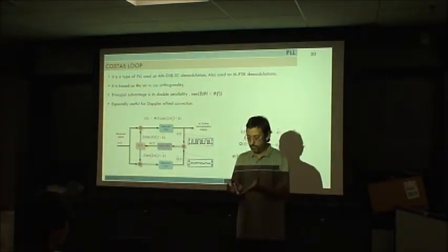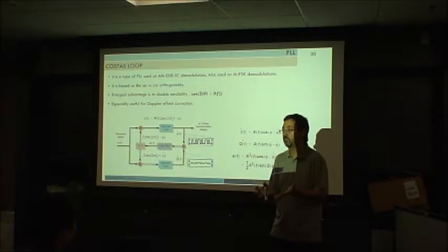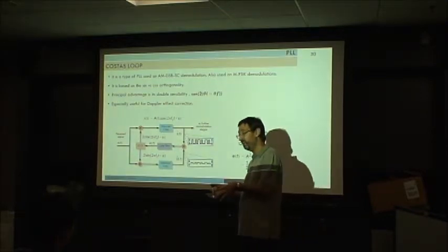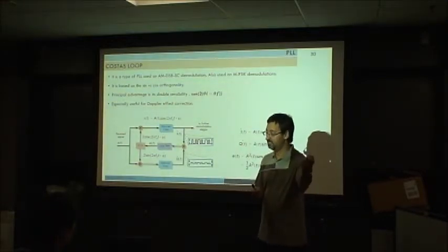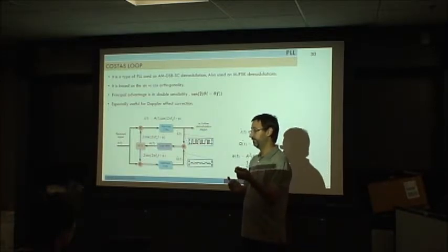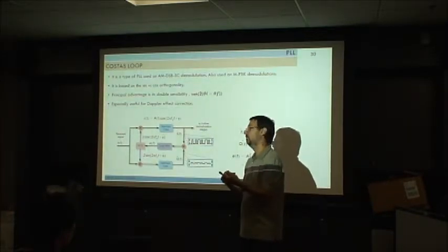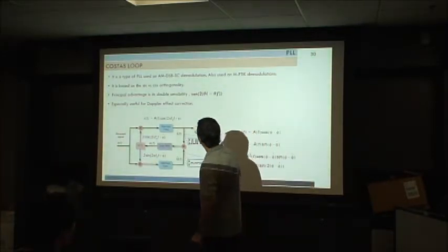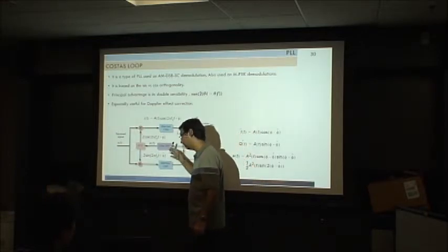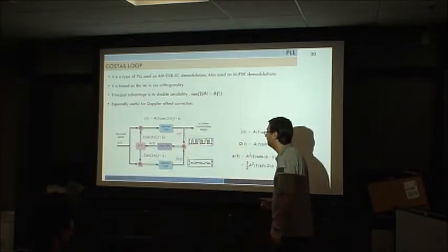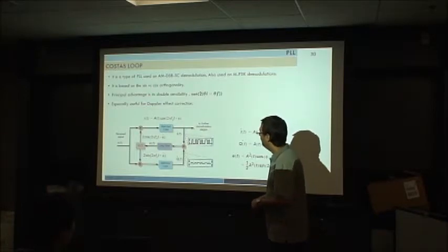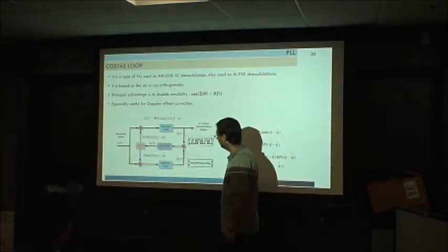So what will we follow if there is no signal to follow? With a PLL you can follow some signal that is there, but in suppressed carrier there is no tone. So this is called Costas loop. The guy that invented it was named Costas. And this is how it works.